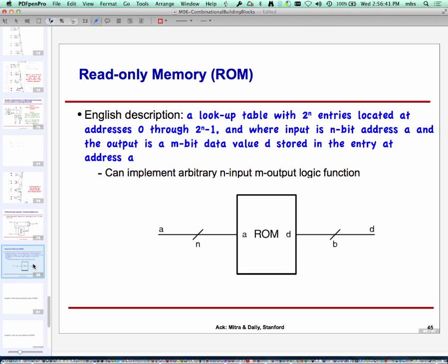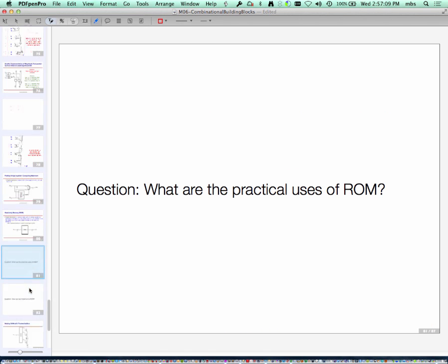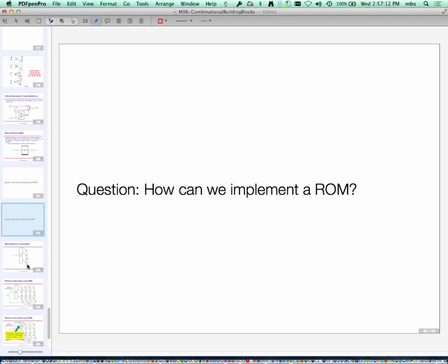So it's a universal combinational logic, right? I just arrange for the factory or my special ROM programming hardware to write the appropriate contents in the different locations, and I have my combinational logic. So you don't have to do any of your Karnaugh map designs or anything like that. You just write the content. You're literally writing the truth table entries into this. So that's the power of ROM. It obviously comes at a cost. It's less efficient than doing it gate by gate with gate logic, but it gives you a general mechanism for doing it.